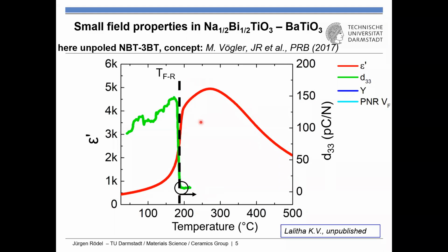So here you can make a lot of models. What is exactly in here? There's supposedly a relaxor with polar nanoregions. And there are very nice techniques to get at it. There's high resolution TEM, and you can determine local polarization vectors in the unit cell. That, of course, is destructive and is statistically not so robust, but locally you get a very nice approach, but you don't really know how much volume of PNR do I have. I don't think you want to use a TEM technique to find that out.